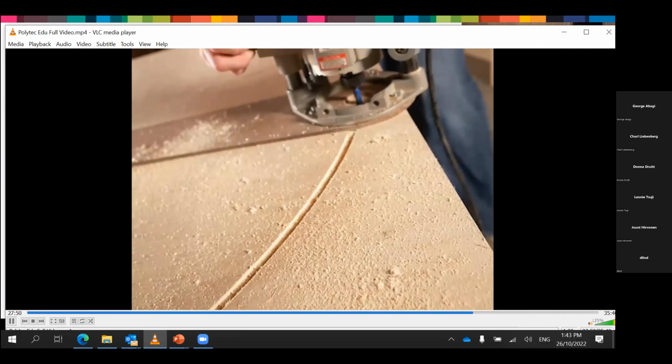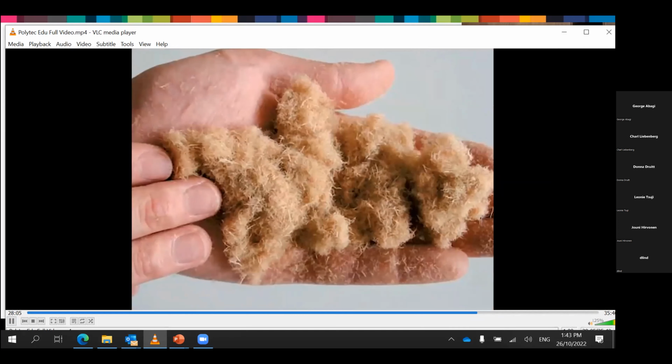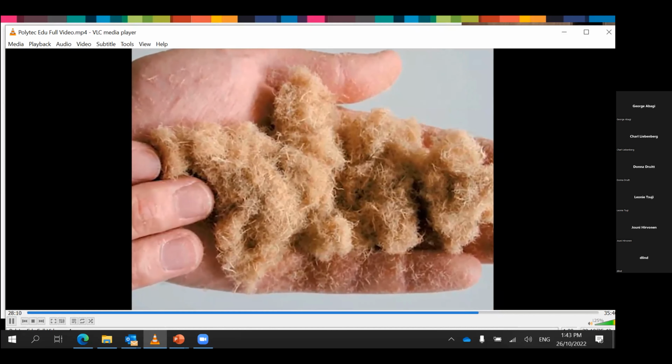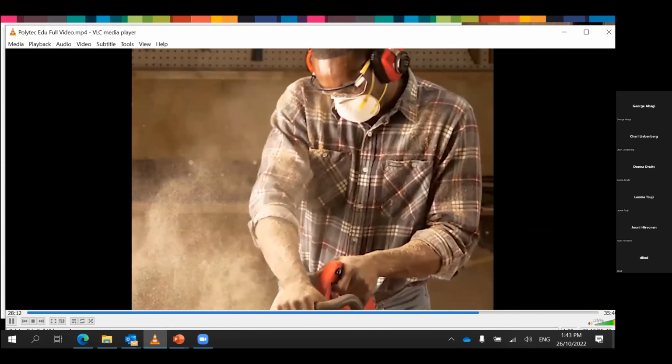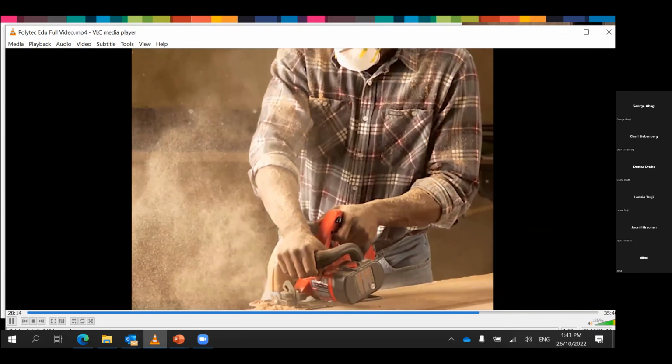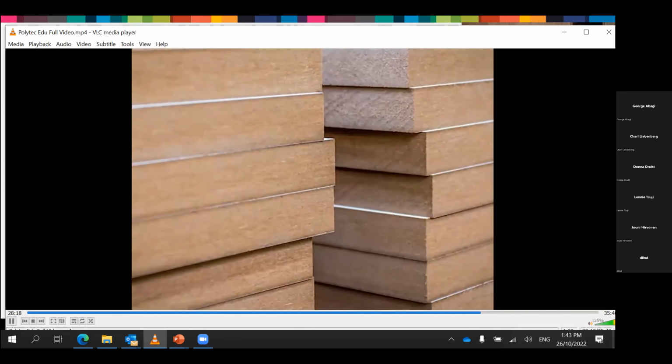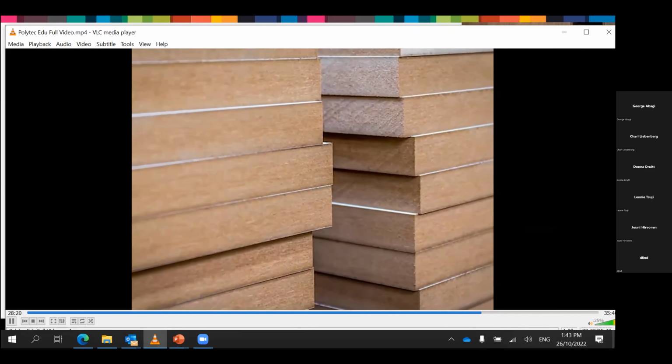Medium density fiberboard is a high quality substrate material that is smooth, and its dense core allows for ease of painting and cutting to achieve precision detail. MDF offers superior screw holding when pre-drilled. Due to its density, it is heavier than particle board and generates more fine wood dust when cutting. This product also comes in a moisture-resistant MR MDF and as fire retardant, E0/E1, EN 13986.